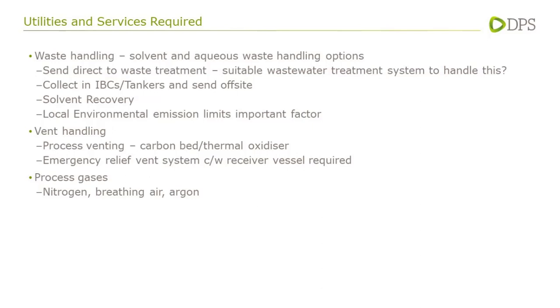Another consequence of the use of solvent is the requirement for nitrogen inertion of all vessels to minimise the risks of explosion. The use of nitrogen has its own hazards, asphyxiation, so the correct infrastructure, O2 monitoring, breathing air supplies and the like, and training are required to facilitate this.